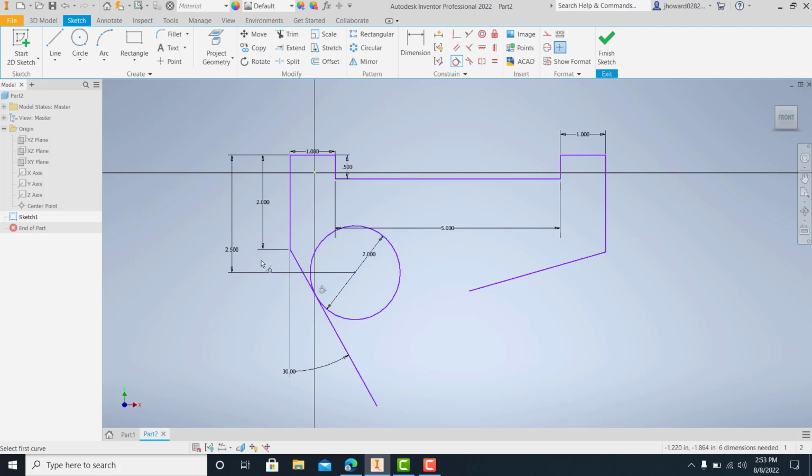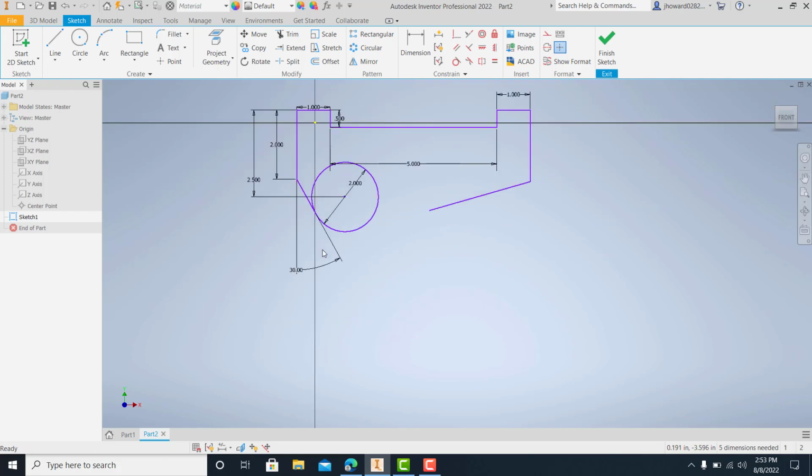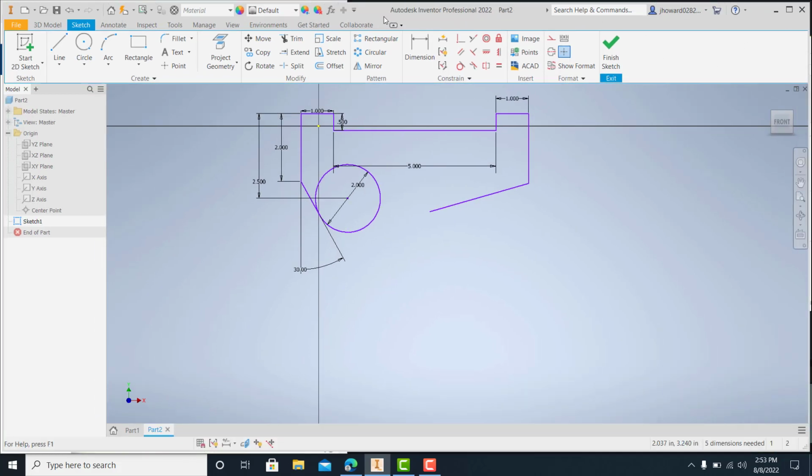So it's going to float side to side, but this is what got my X direction located. And you see the little tangent symbol? That made a tangent right there. And I can trim off this excess by hitting trim and come up there and trim that out. So there that is. And I want to minimize that. Hope you all caught that trick.